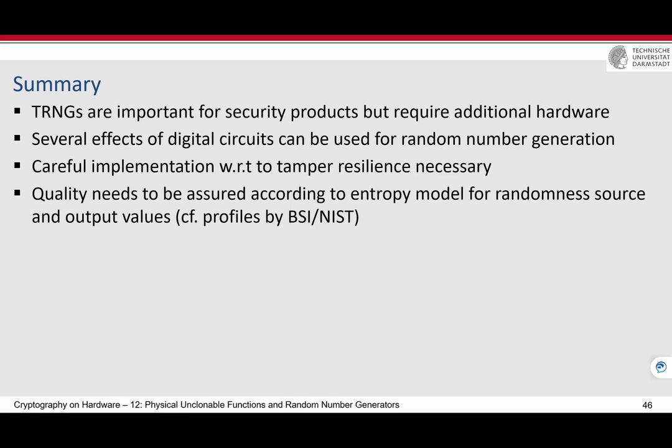And if that is the case, then you know that, for example, the seed of your PRNG is always 0 or always 1. And if you turn your device off and on, always the same sequence of random numbers is generated. Of course, they are random, but if every time you turn it off and on the same sequence is generated, these are dangerous things. And for that reason, as I said, usually the output of the TRNG should be checked online. And of course, if you build something as a random source, then you need to run a couple of tests and statistical tests to check whether the quality of the random numbers is good enough for different applications.